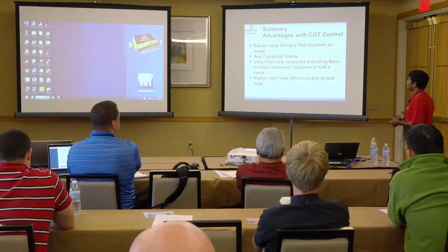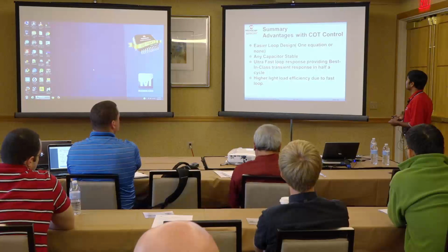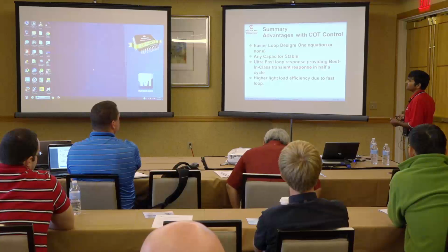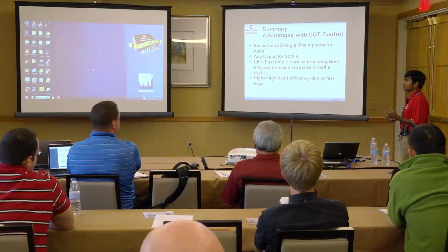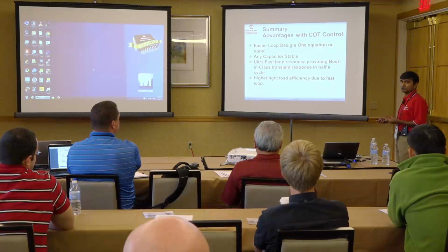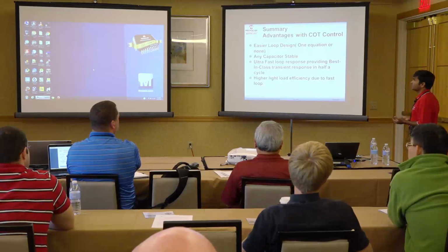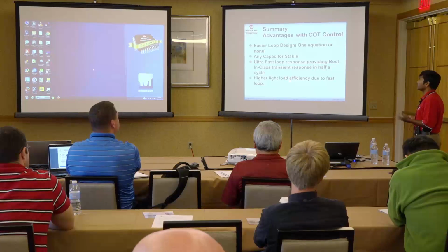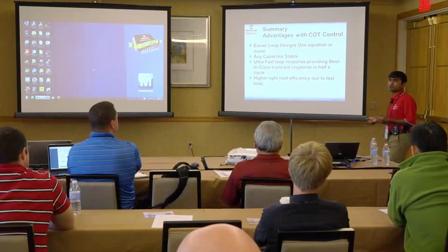The other major advantage of constant on time control is ultra fast loop transient response, providing best in class transient response in half a cycle. That is not the case with any fixed frequency controllers. Another inherent advantage we get from the COT controllers is hyper light load efficiency, which is very much required for battery powered systems.